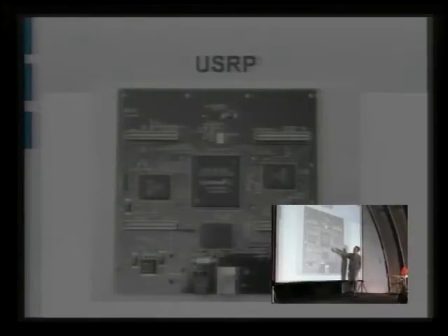And in here we do what I showed on the last slide, which was the digital up and down conversion and the decimation and interpolation, other filtering operations, timing control, that sort of thing. And then these connect to these 2 chips. Now, each of these chips has a dual high-speed A to D and a dual high-speed D to A converter, plus a couple other functions. So this is kind of our analog codec. It takes digital to analog and analog to digital, and there's 2 of them.